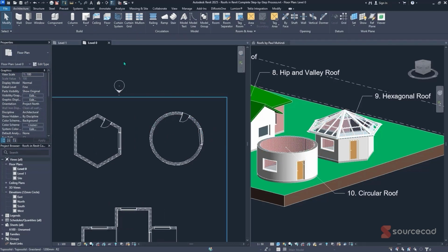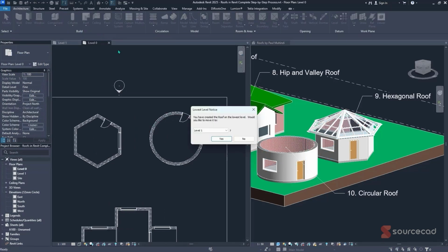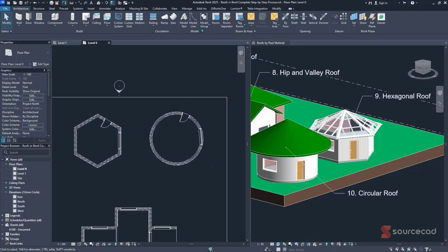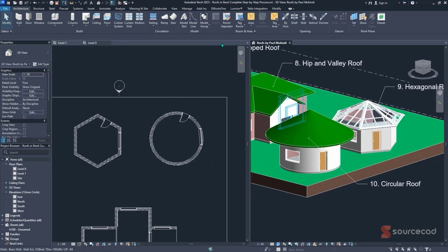So how do we do a circular one? It's still the same thing. Footprint, select level 1. You can opt to start with a completely new circle from the center, then draw your specific circle. This is important, especially in Africa, where we usually have roofs for our huts, and this is simply how we can come up with a simple design.